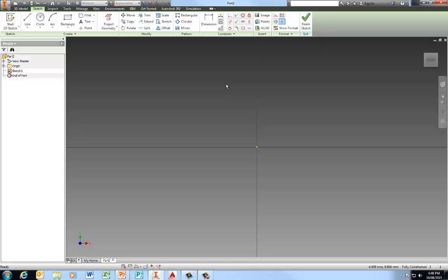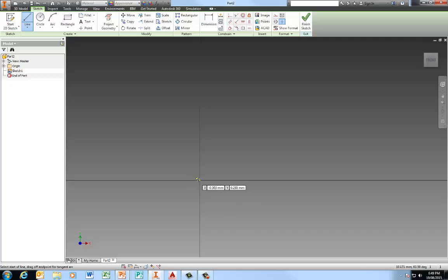The volume that profile sweeps as it revolves around 360 degrees then creates our solid form. So let's get started with our first sketch. I'll draw a line and I'll start by snapping it to the origin point so as I don't have to manually incur the coincident constraint later on.